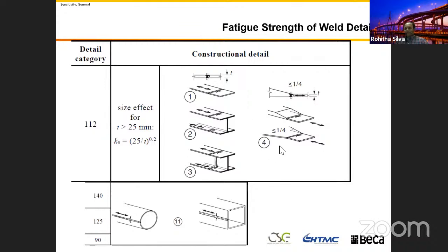calculate. So in addition to that, when you are going to do the fatigue detailing and design, you need to make sure you follow the design code, you detail that one, you make sure during construction you test and you confirm your design is working. You make sure that your quality assurance system is put in place to ensure that your weld is right.